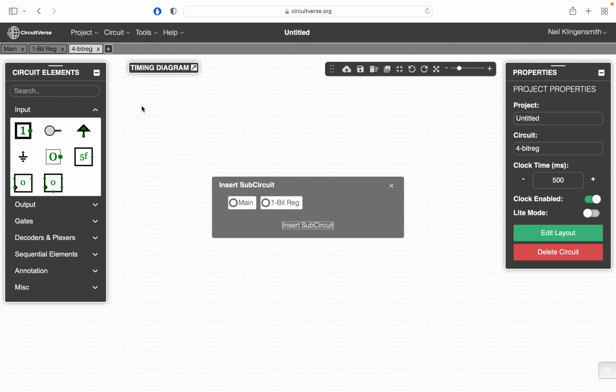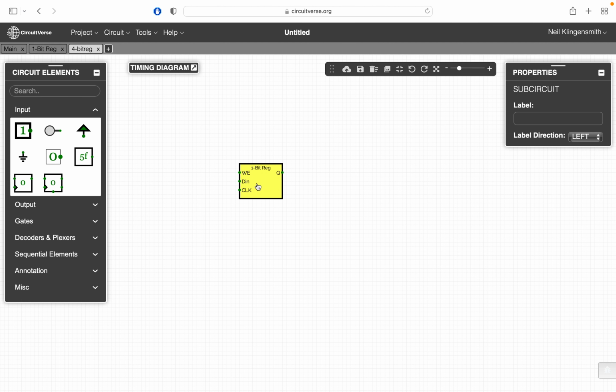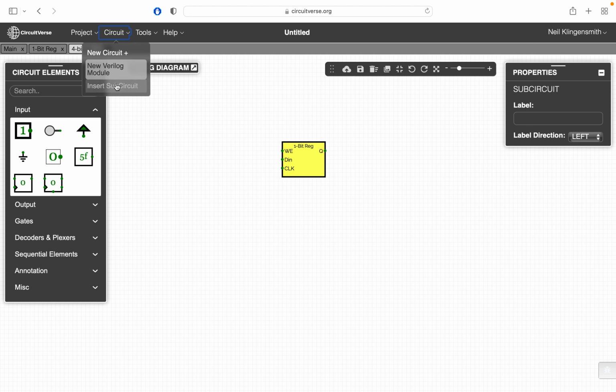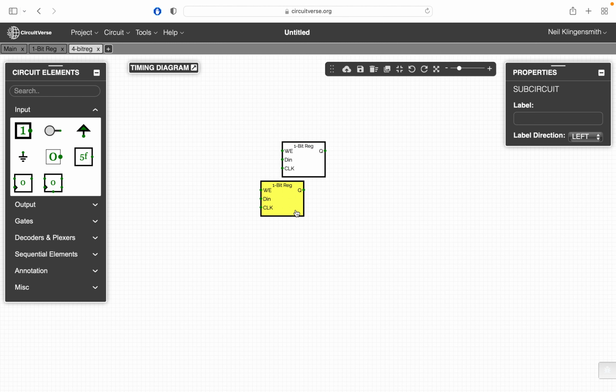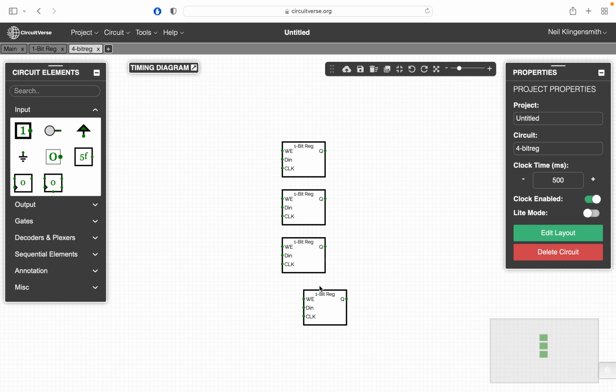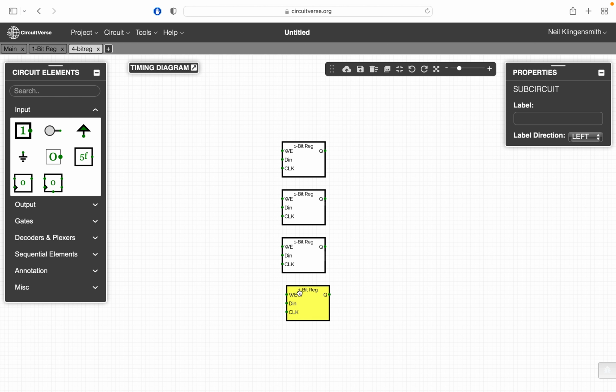While I'm doing this, I want to remind you that if you look at the way I route the wires in this design, you'll notice I'm trying to keep everything spaced out and orthogonal. I've seen a lot of students, when they get into these digital designs, just route wires using the shortest path from one point to another without worrying about keeping things spaced out. What ends up happening a lot of times is that they get unintended wires crossing each other, and it completely screws up the design and it won't simulate correctly inside Circuitverse.